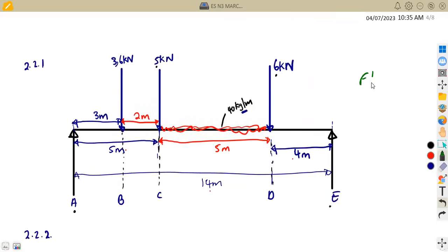So the force per meter is going to be mass times the gravitational acceleration per meter. That is the mass of 40 kgs. So that's 40 times 9.8, whatever you're going to have, it is going to be in newtons per meter. So what is going to be our force per meter in this case? If you multiply properly, this is going to give us 392 newton per meter.